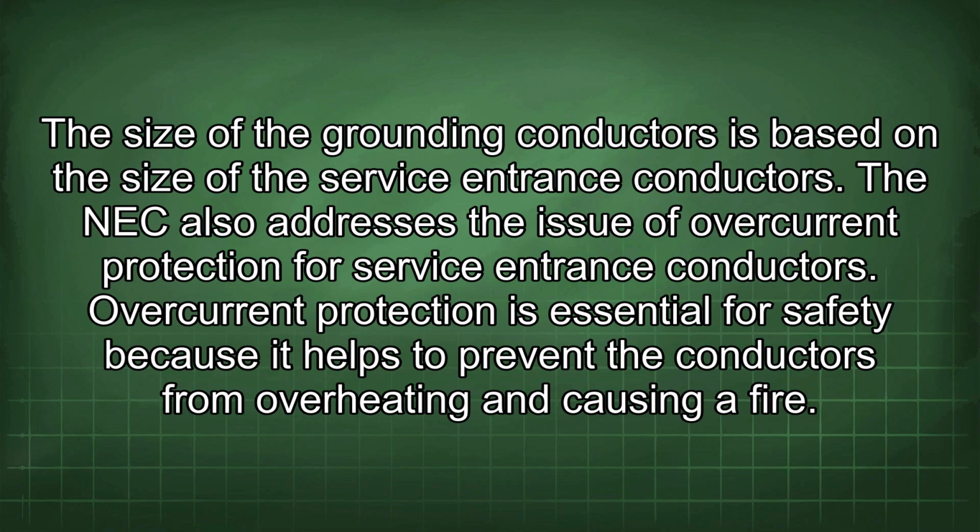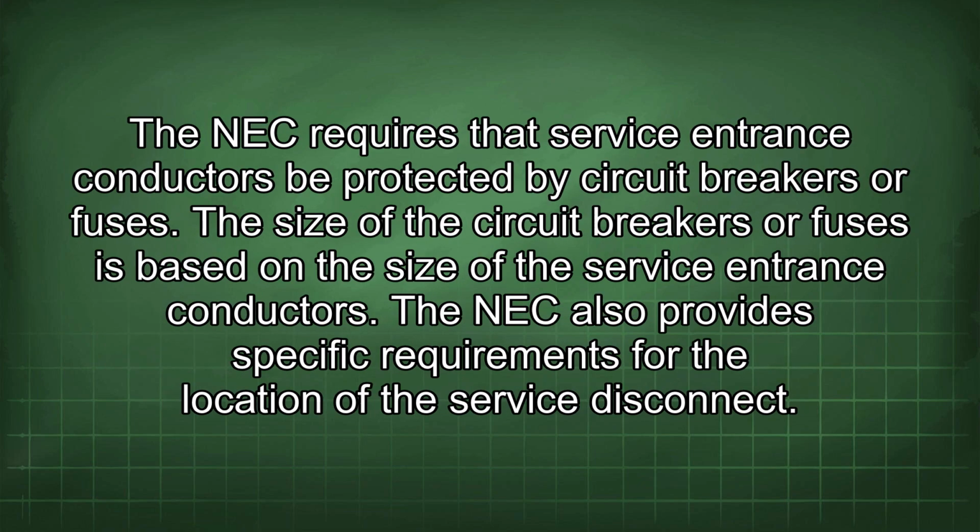The NEC also addresses the issue of overcurrent protection for service entrance conductors. Overcurrent protection is essential for safety because it helps to prevent the conductors from overheating and causing a fire. The NEC requires that service entrance conductors be protected by circuit breakers or fuses. The size of the circuit breakers or fuses is based on the size of the service entrance conductors.